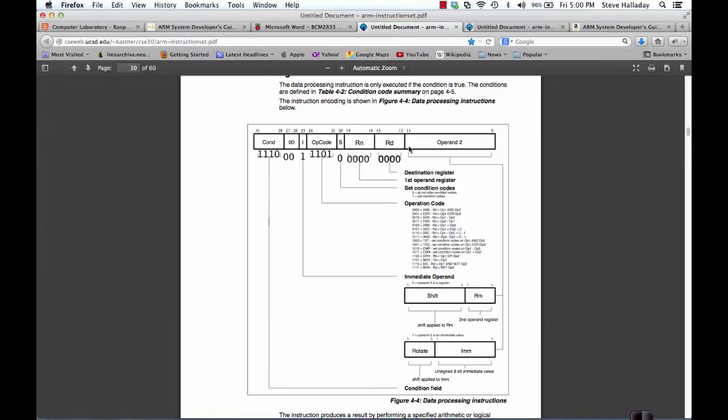The first instruction will just move in the value 0x20000000, and then the next instruction will load in the value 0x00200000 into another register, and then we'll OR these two registers together to get the final answer of 0x20200000.